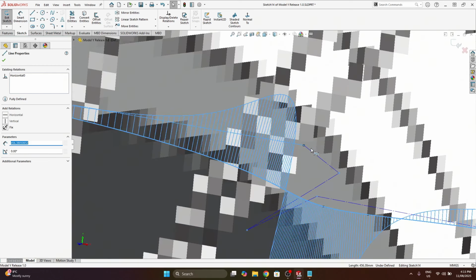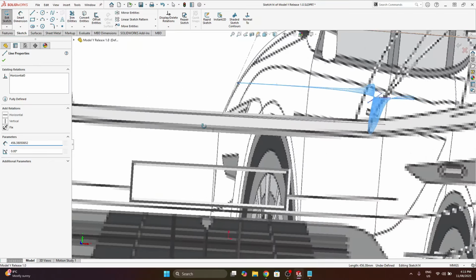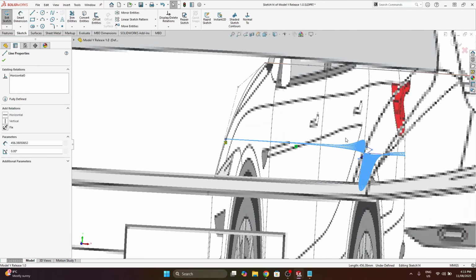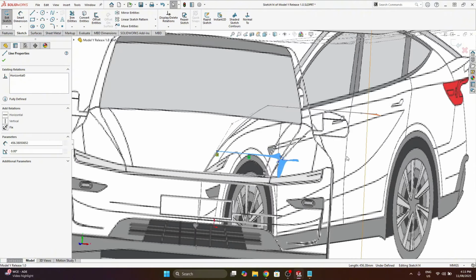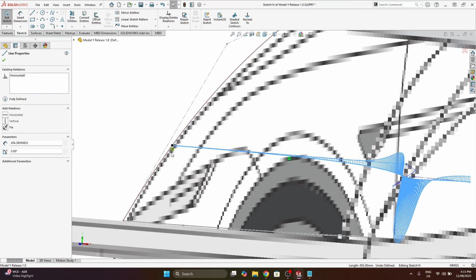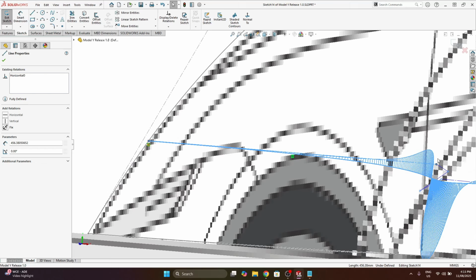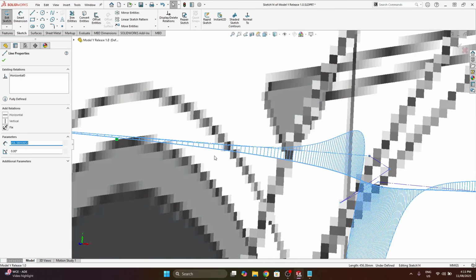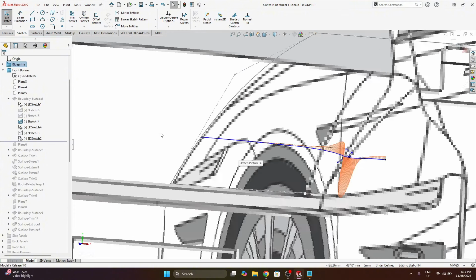the construction line to the first CV I've set as horizontal. So essentially what that means is that when I mirror this over, because I'm just modeling one half of the car first and then mirroring it later just to ensure that the car is symmetrical, anything that's touching the mirror plane of this car, you want your guide curves to be horizontal up to 1 CV, and that will ensure you get a nice tangent transition across.